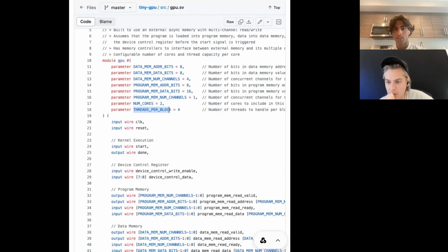Good question. So the sole reason for this, and this is the reason behind my memory intuition and why George Hotz said the whole problem is memory. We'll see that when we dive into thread execution. If there was no reading and writing from memory, it would all finish at the exact same time, because everything is deterministic there. It just takes the same amount of cycles for every instruction. The thing is, when you have memory, like loading from global memory, that memory is DRAM. So first of all, it's using capacitors to store memory, it has some latency to it. You don't just get it back in one clock cycle instantly, which has some non-determinism.